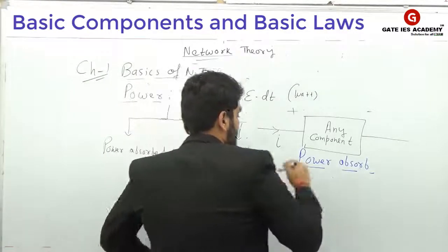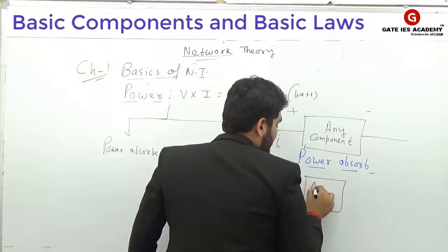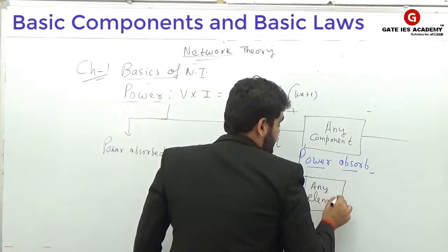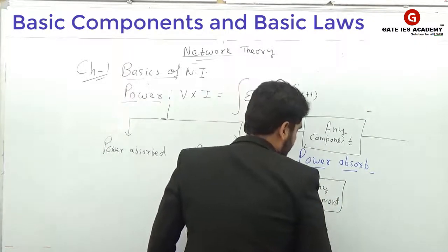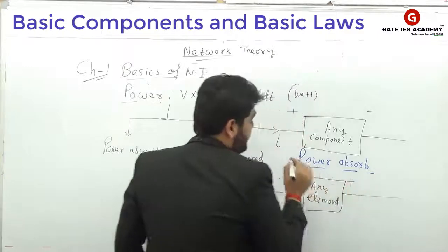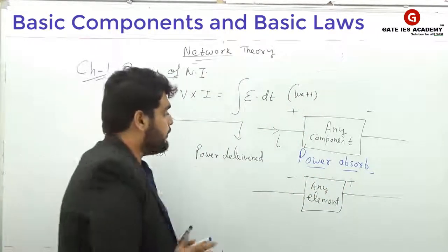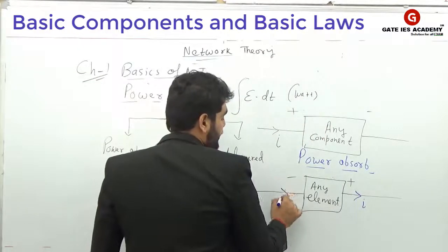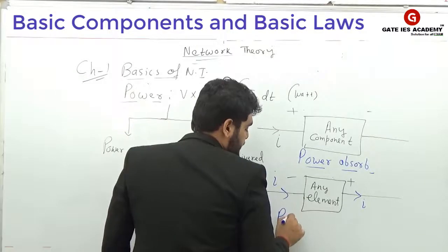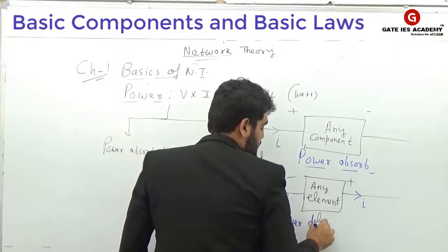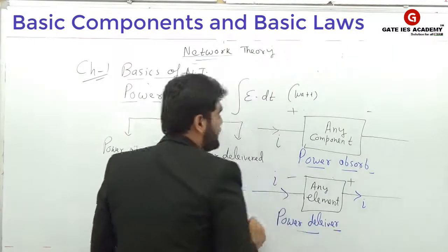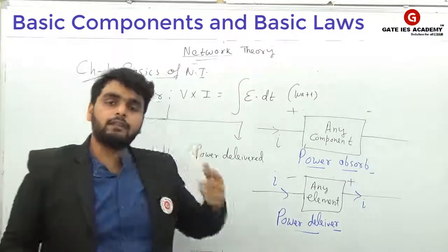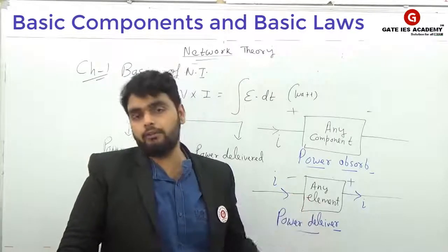In the same case, if you have again any element, it can be active, passive, linear, non-linear, anything. If current exits from the positive terminal, or you can say enters at the negative terminal, it means power is delivered. So always remember, in this way we have to identify whether power is being absorbed or delivered.